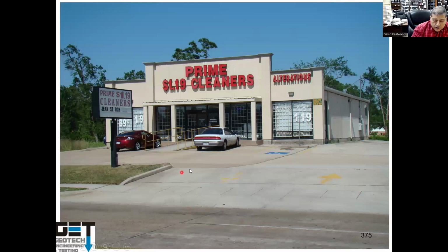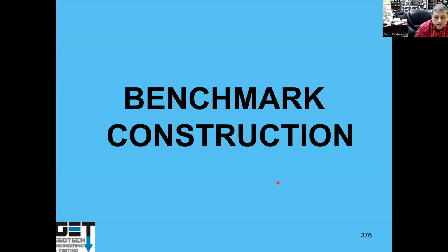This guy here, they put concrete all around the building. So in this case, once the building becomes stabilized after initial movement, it doesn't move anymore because there's no change in moisture. Remember, movement occurs because of change in moisture. If your moisture doesn't change, it does not move. So usually major movements occur when the soil goes all the way from dry to wet or from wet to dry. So that's what happens. But if your moisture doesn't move, you don't have to worry about movements.